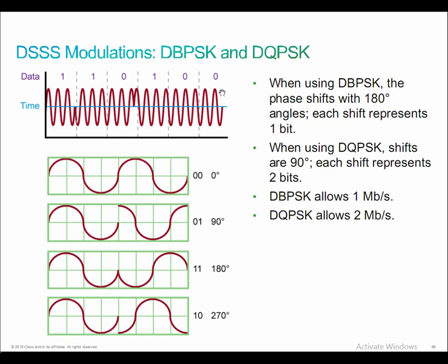It's pretty straightforward when you look at the modulation technique, right? Remember, the Barker code allows us to send a chip of 11 digits, or symbols, bits I guess you could say, instead of the value itself, so that the signal can go through interference and still be understood. It makes a lot of sense.